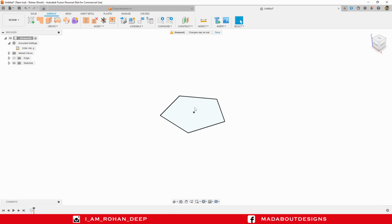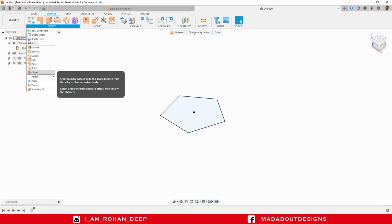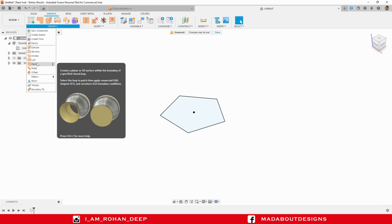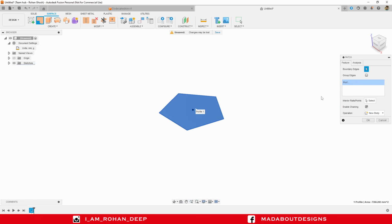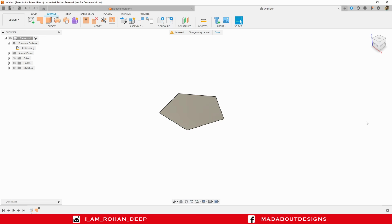In order to make this sketch a surface, go to Patch, select this profile and enable chaining option, operation new body, click OK.